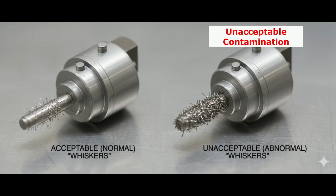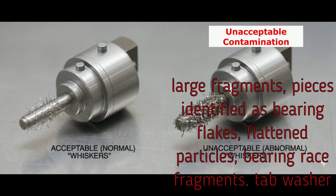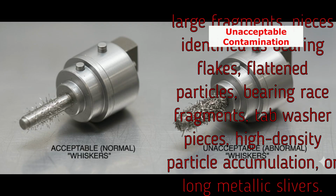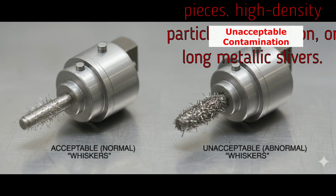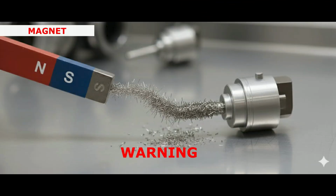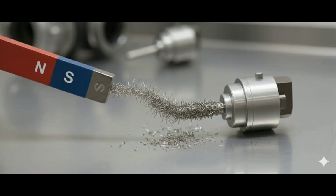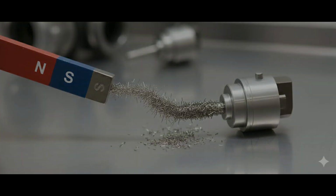Unacceptable contamination. This includes large fragments, pieces identified as bearing flakes, flattened particles, bearing race fragments, tab washer pieces, high-density particle accumulation, or long metallic slivers. Warning: do not use an external magnet to clean the particles from the magnetic plug. The use of an external magnet may degrade the magnetic performance and sensitivity of the plug.